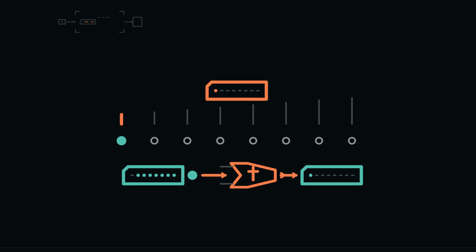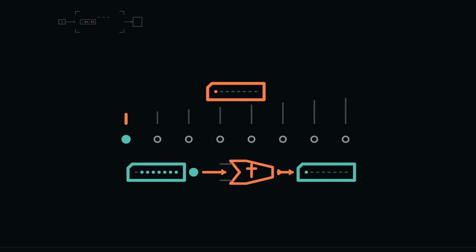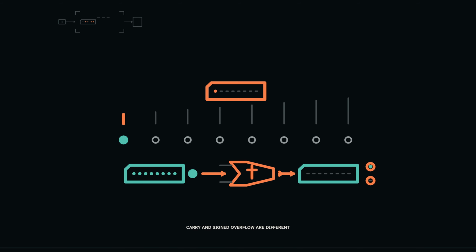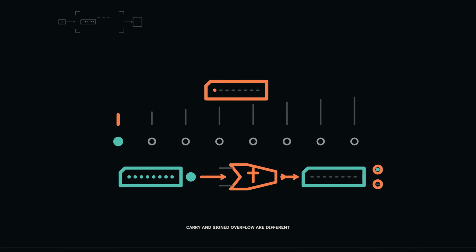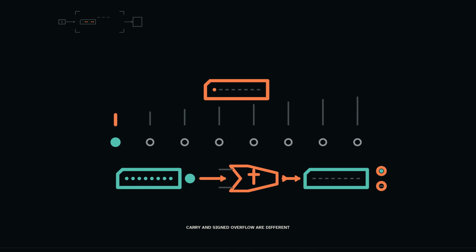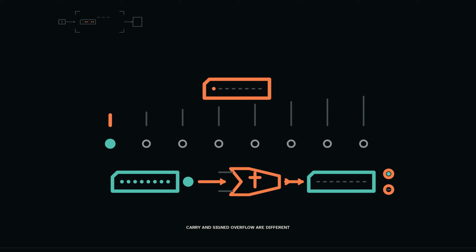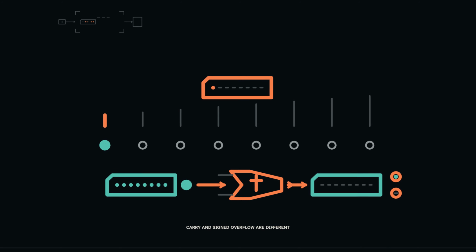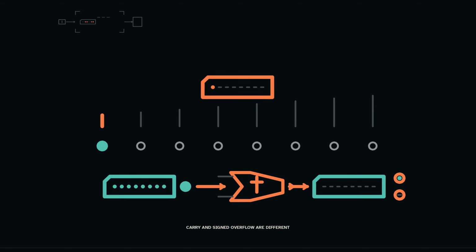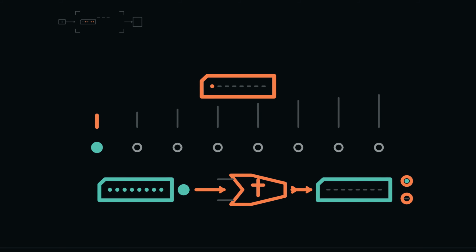The signed answer has crossed from the largest positive value to the most negative one, so the overflow flag must report that failure of the signed range. Carry and signed overflow answer different questions. In 255 plus 1, a 9th unsigned bit is needed, so carry is set; interpreted as -1 plus 1, however, the signed result 0 is valid, so signed overflow is clear. In 127 plus 1, no carry leaves the 8th position, so carry is clear, but 2 positive signed inputs have produced a negative signed result, so overflow is set. Neither flag is a general warning light. Each preserves one precisely defined fact about the same fixed width operation.